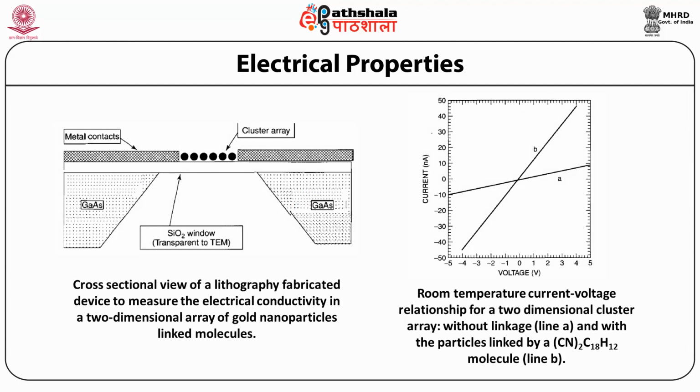For a collection of nanoparticles to be a conducting material, the particles must be in electrical contact. One form of bulk nanostructured material that is conducting consists of gold nanoparticles connected to each other by long molecules. This network is made by taking gold nanoparticles in the form of an aerosol, sprayed and subjected to a fine mist of thiol such as dodecanethiol, RSH, where R is C12H25.